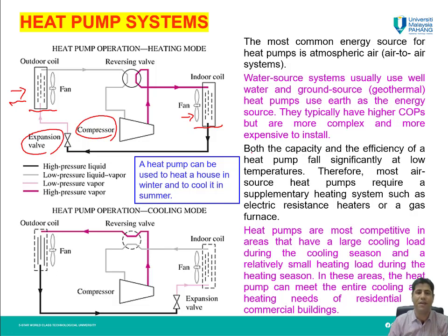This kind of heat pump also has higher efficiency, but it costs to put these facilities inside the ground. So the COP will be higher when the medium which we absorb energy from is the earth, but it is more complex to install, and it will cost more than the air based source of energy.